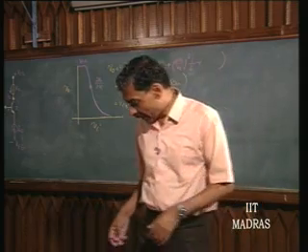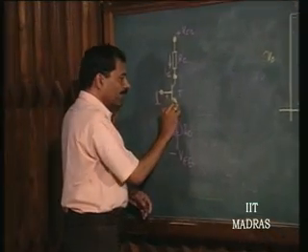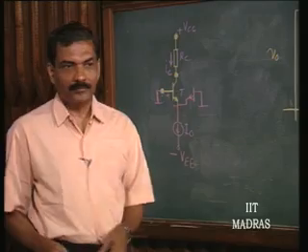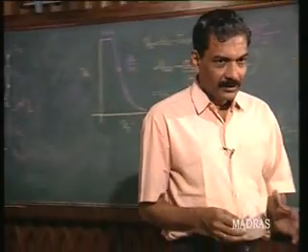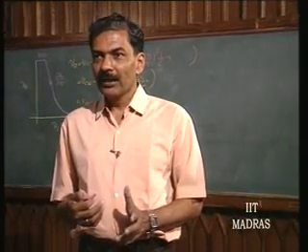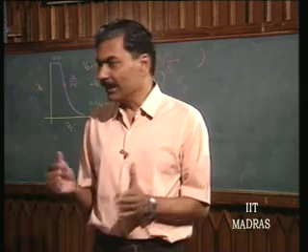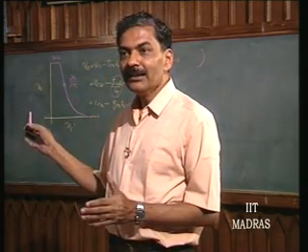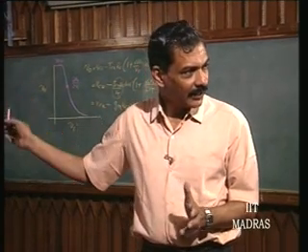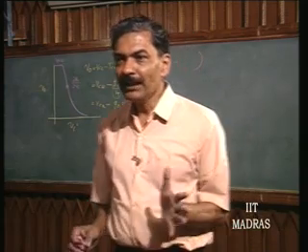In this case, therefore, I have to put a device here. What will be the device that I will put? Automatically I will put a forward biased diode here. Please understand this, because a forward biased diode is a short circuit for signal. But what will it do to this current? Because of the IC property, the I naught is going to be split equally, because bases are connected, emitters are connected. So, these are identical transistors, and therefore, the currents have to be equal.